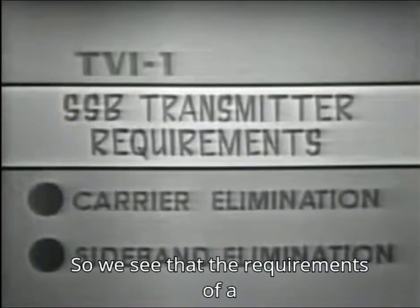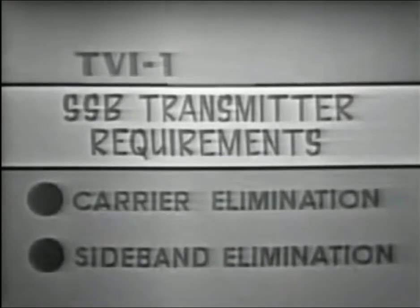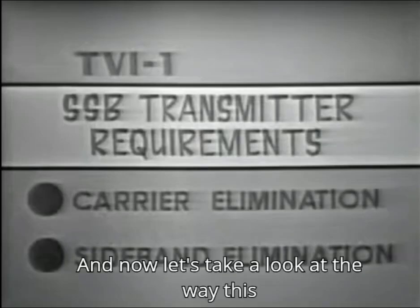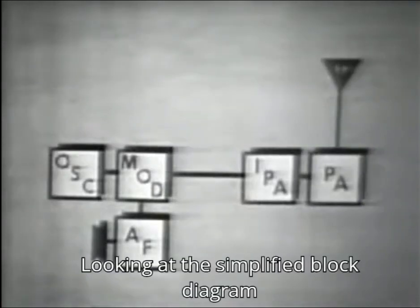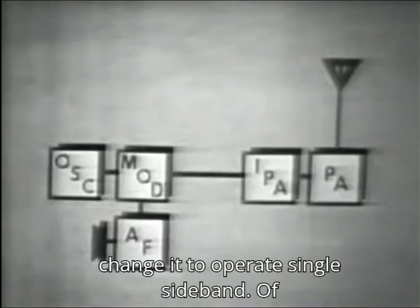So we see that the requirements of a single sideband transmitter must be elimination of the carrier, elimination of one sideband, and now let's take a look at the way this is done. Looking at the simplified block diagram of a conventional AM transmitter, let's change it to operate single sideband.